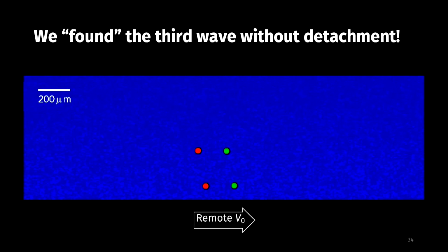Now, the experiments I showed you didn't reveal this particular Rayleigh wave speed crack. Right? They showed you two waves going in opposite directions, both had detachment and so on. But if you probe this reasonably carefully and play around with the parameters a bit, you can, within quotes, see the other wave. Now, there's no detachment, so you have to put cross polarizers into photoelasticity and recover the stress field. But you can see the signature of that in the experiments.